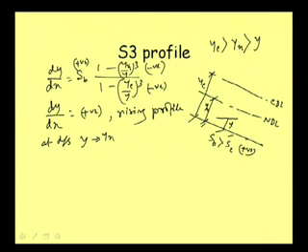We have discussed several times, when y approaches yn, then dy/dx becomes 0, and this physically means that y tends to become yn asymptotically.